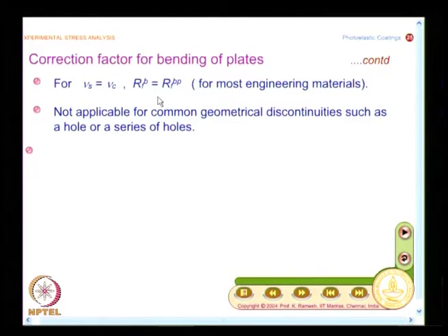These are all the developments in the old days where they had only slide rule to work with. Now you have computer software available, you have to just put in your thickness of the specimen and thickness of the coating and material properties. You can even select it from a database, you instantly get the correction factors. Even if it is not available, you can write your own code. So, the days are different now, though the expressions look very long and unwieldy. It is necessary even to do simple calculations in reflection photoelasticity, you cannot ignore it.